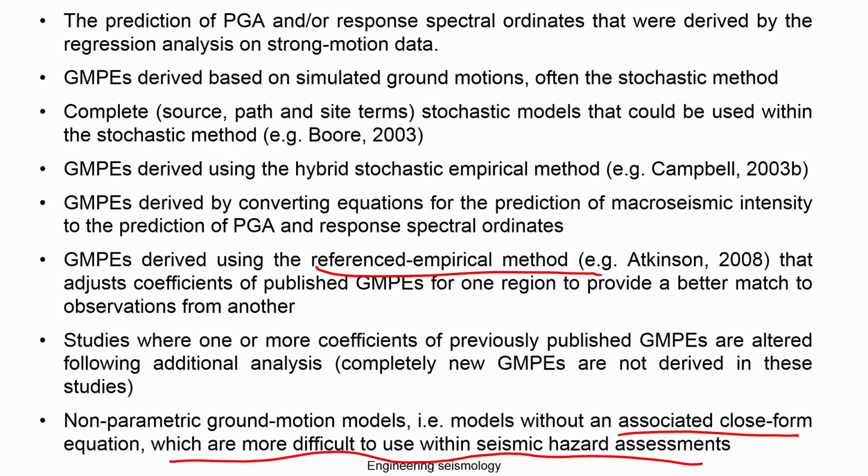We consider bedrock condition for all the data; we do not mix soil site data with bedrock site data. For that purpose, even in the available data we try to separate which sites are soil and which are rock. Again, soil types 1, 2, 3, different classifications we have done. You can also find that kind of paper there.